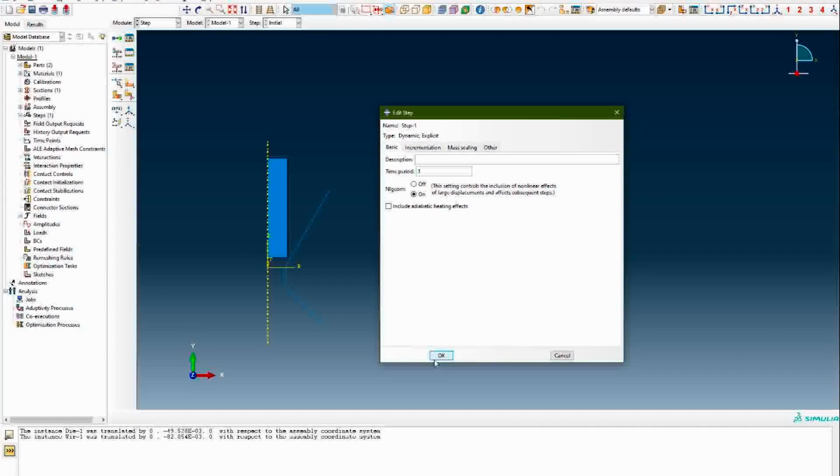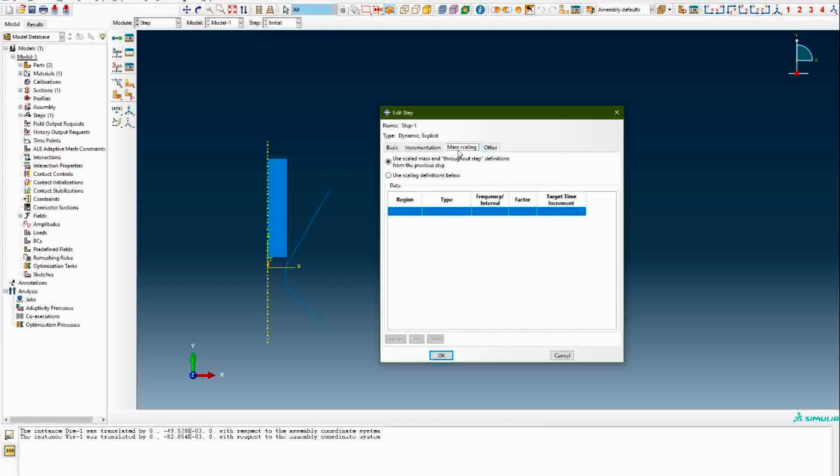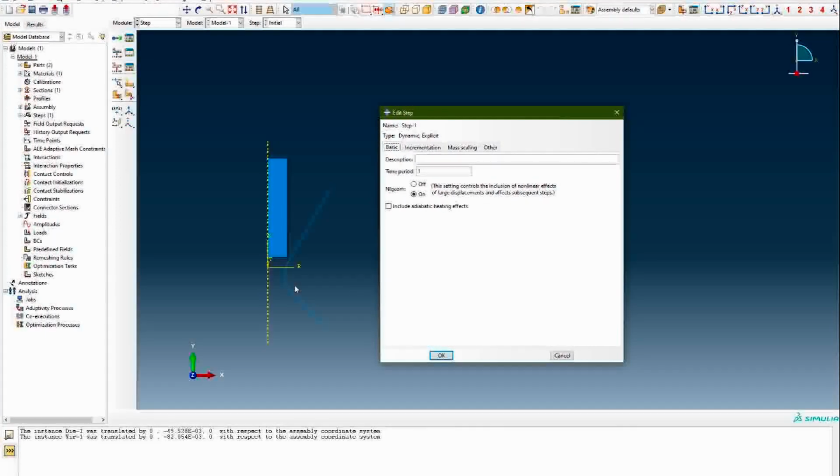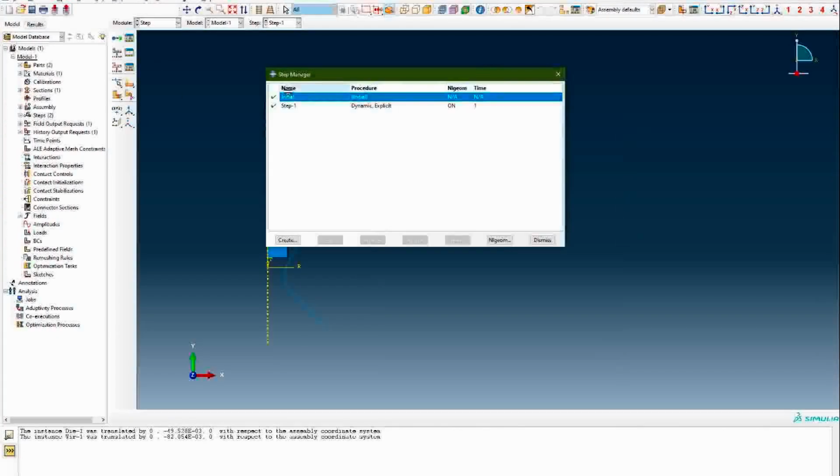So just leave these other three sections here. I will explain them in other videos, but this video is only for very beginner students who just want to know how ABAQUS works. So consider the time period as 1 and click on OK. So you can see one step is created.